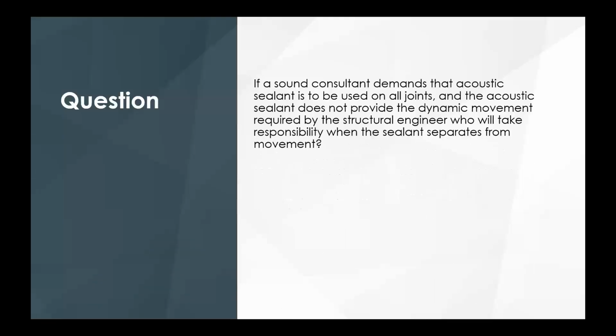All right, question for everybody here. If you got a sound consultant that demands acoustic sealant be used on all joints, and I've seen this a lot, and the acoustic sealant does not provide the dynamic movement required by the structural engineer, who will take the responsibility when the sealant separates from movement?